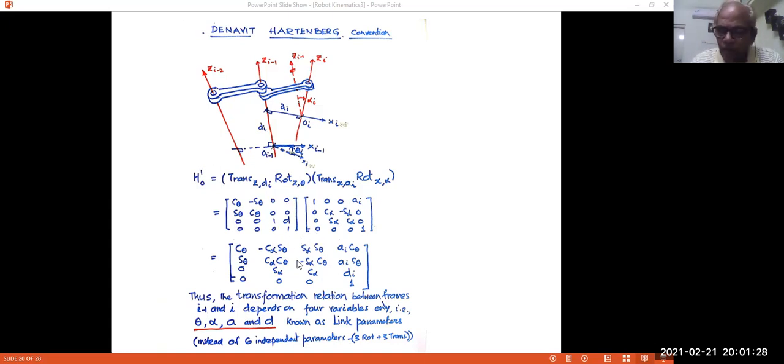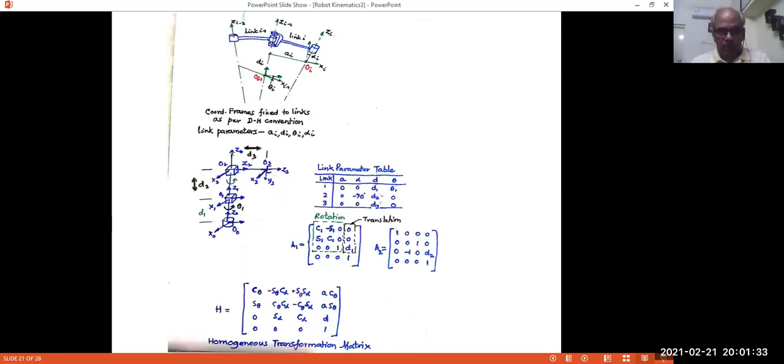Well, we'll take an example. Suppose you have a cylindrical type of arm. You have a rotary joint, a prismatic joint which is moving like this, and a prismatic joint which will make the link move like this. So this is the end point to which your gripper, let us say, or some wrist or gripper will be attached. For the present, we will say it is the gripper attached to this point. We fix a frame there also, at the end of the last link.